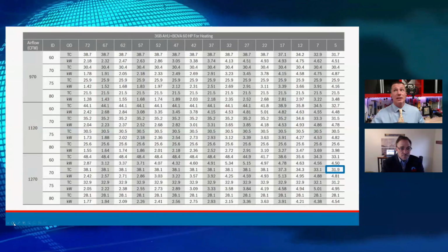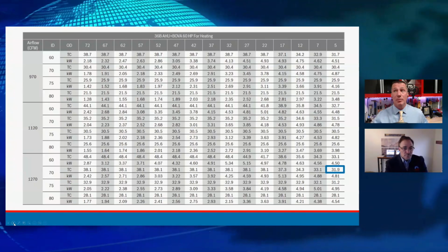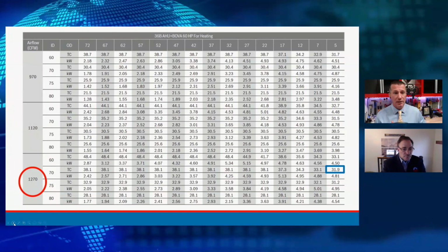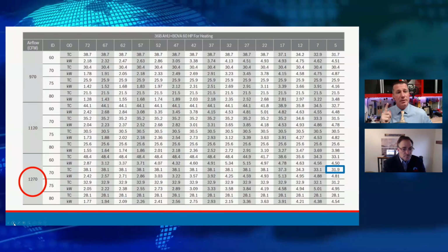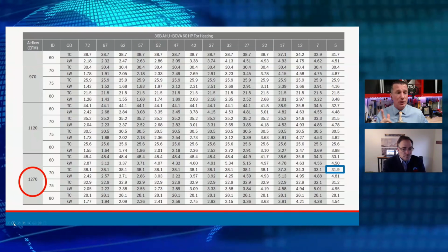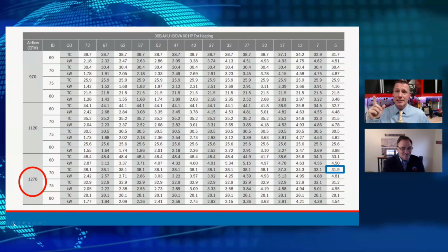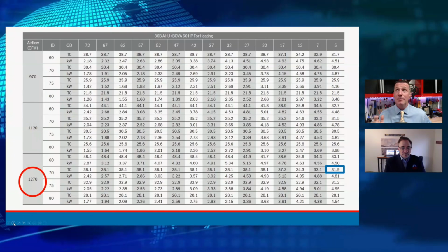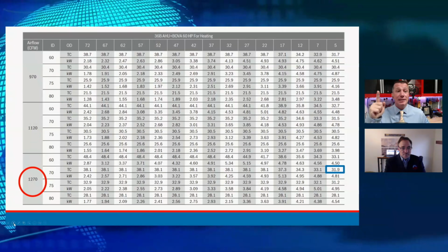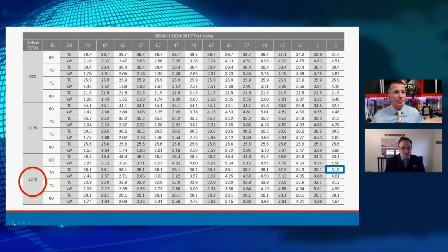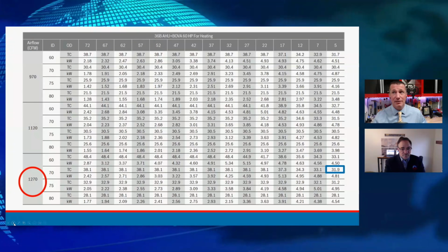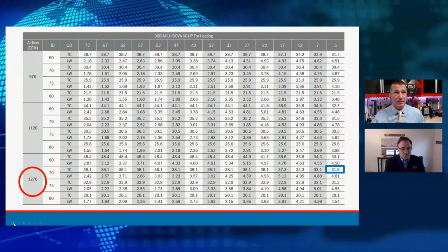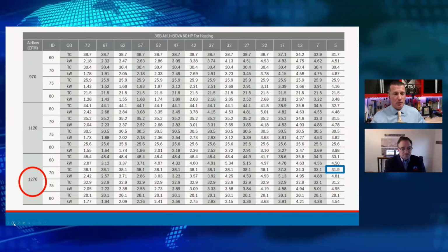So we have to set the blowers up to be able to handle the airflow properly. This is where we see these higher heat capabilities. There's 32,000 BTUs, but now I've got to move a lot of air to do that, whereas with some of the manufacturers, you can move the BTUs with a lower fan speed. Some of this technology requires a fairly high CFM. At 5 degrees, this particular unit needs to move 1,270 CFM to get our 32,000 BTUs at that 70-degree dry bulb.